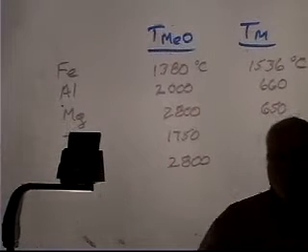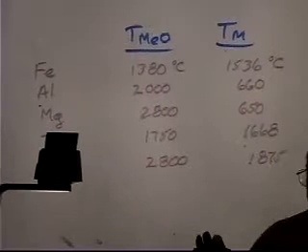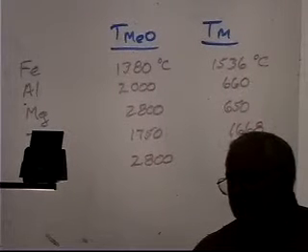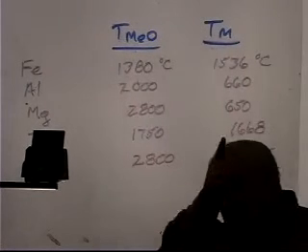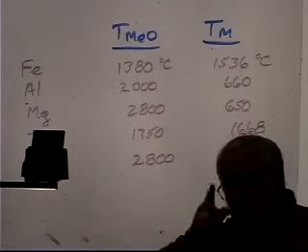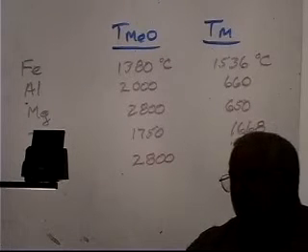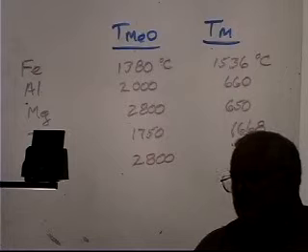So that's a pretty important process, oxyacetylene cutting or oxy-fuel cutting. You don't have to use acetylene because all you're doing is preheating it. You can turn the flame off after you start the oxygen jet. In fact, in a steel mill, when you have hot steel coming out of a casting machine that's solidified, and it's still about 1300 degrees centigrade, they don't even preheat it. It's already heated.